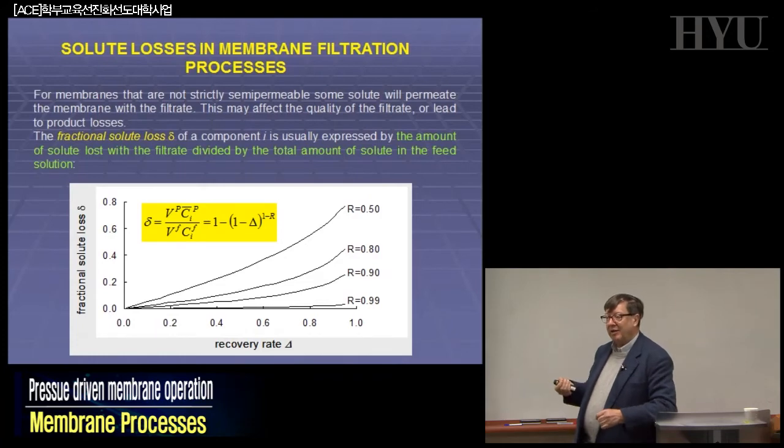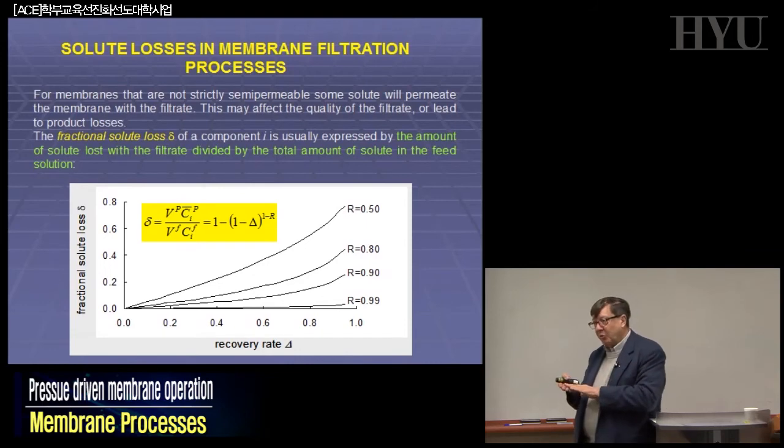White spots come from the fact that the coatings are always a little bit permeable to water. So with time, if any drops of water were still present on your electronic device, the water evaporated across the coating, and the salts, a few molecules left behind, which could not go through the coating, precipitated at high concentration, creating the white spots.